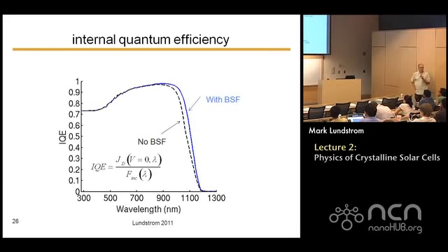It's the percentage of electron-hole pairs that were collected. Now if you sweep that as a function of wavelength, you'll get some information about what's going on. Because the short wavelengths have high energy, they're absorbed very near the surface, and that'll tell me something about recombination near the surface. The long wavelengths are absorbed more deeply, and they'll be more sensitive to recombination in the base or at the back surface contact.